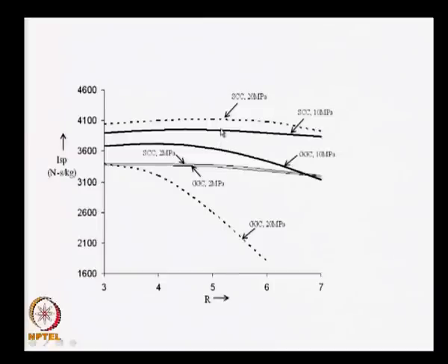Please remember that the x axis in this graph represents the overall mixture ratio R, and as R increases, the quantity of the oxidizer increases. Since we are in an oxidizer rich region, there is a fall in pressure as the mixture ratio increases. If I go to something like 20 MPa, say 200 bar, because of the very high value of F, my GG cycle has this performance, whereas I do not lose anything in a staged combustion cycle. This is the performance. Therefore, I lose a lot by operating a GG cycle and not a staged combustion cycle. This is the net inference I get.